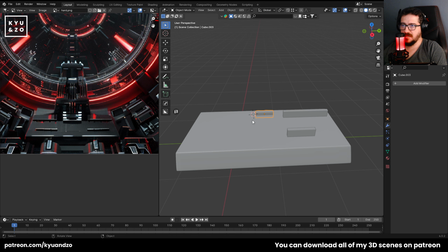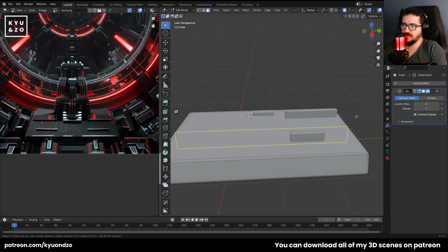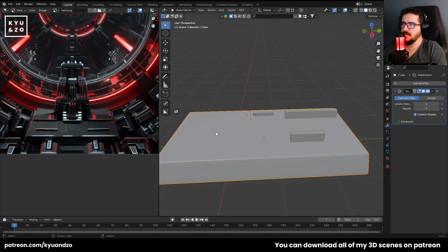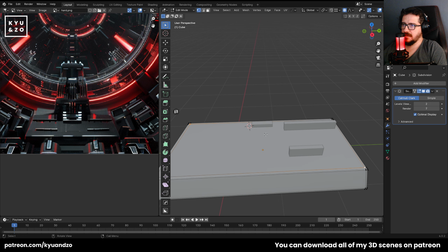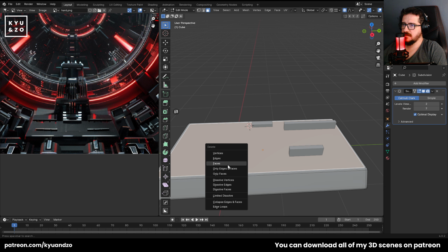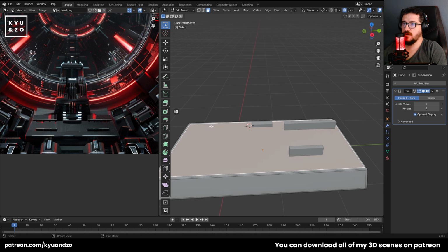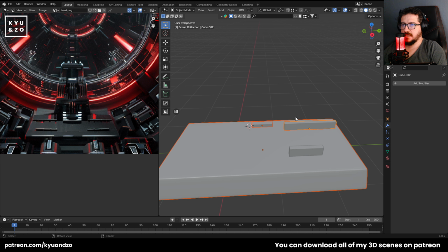Let me introduce my shortcuts. I'm using Control R. I'm using, for example, connecting it with J, F, delete the faces. Oh, by the way, I'm using Z for move collection. It's not Z in the standard way, but it's under my hand.